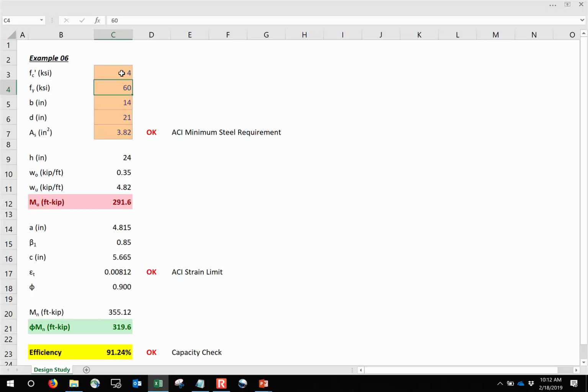But what you can do is change, let's say, the girder spacing. Because changing the girder spacing would change the tributary area, which is going to change the live load reduction, which is going to change the live load on the beam. So now doing that would also... The sheet would get bigger. Well, and it would decrease the numbers we needed for those specific records, right? Yes. Yeah. So that would be the way I put it.